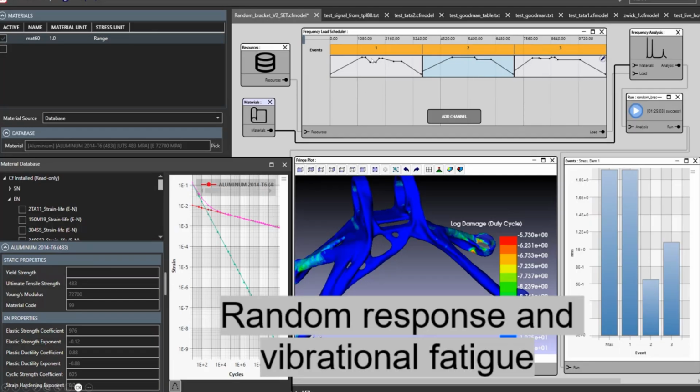So power spectral density, in this case, is a simple example where you have X, Y, Z, so 3 different axes of vibration. And then you will have essentially 3 subcases in Nastran or whatever, in ANSYS and so on. So X direction vibration with a certain exposure, Y direction with another exposure, and then you can check what direction is giving more damage. Okay, and this is just a very simple approach. We can do cross-correlated examples where you have 3 channels or 200 channels acting simultaneously.